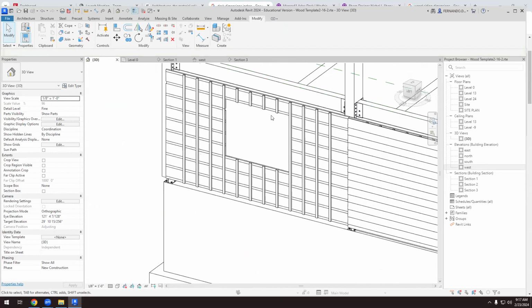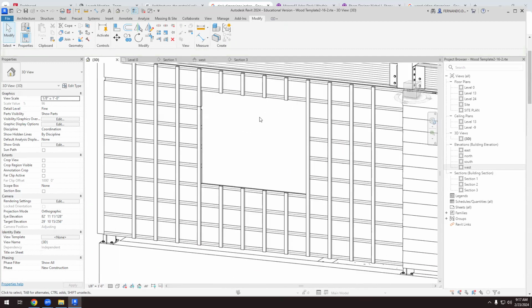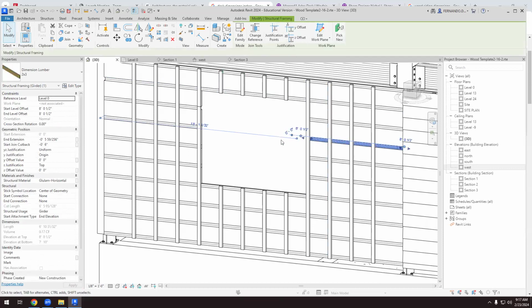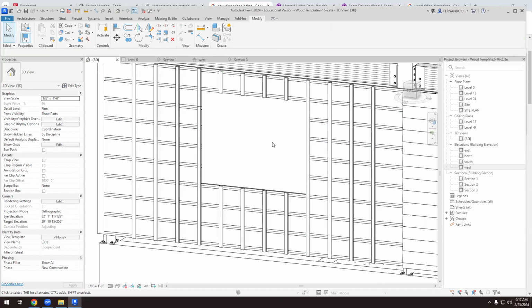So we're carving our way through the wall. We have to go layer by layer. First, I cut the vertical elements. Second, I cut the horizontal elements. Then I have to open a void on those stripes of thermal insulation. So I still have to open a void of this board, then the thermal insulation, then that board again, and finally those vertical elements.